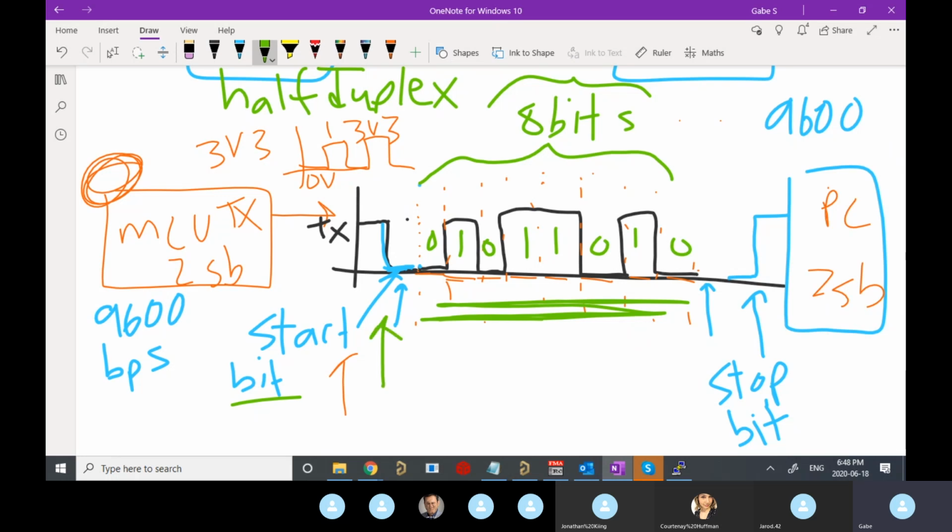So they do a start bit, send their 8 bits of data, and then they leave it low for another start bit. And then they keep hold of this line and keep sending more and more data. And so if it doesn't do this transition of low to high here and stay high, then it may expect more data to show up. And that just saves time, so you don't have to stop and then wait and then restart another start bit, send your 8 bits of data, stop, then wait, then restart. You can just say start, send data, and then keep sending more and more and more data if the slave doesn't receive the stop bit.